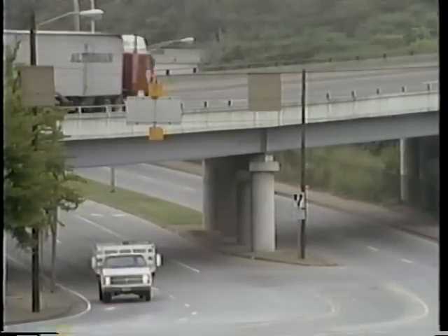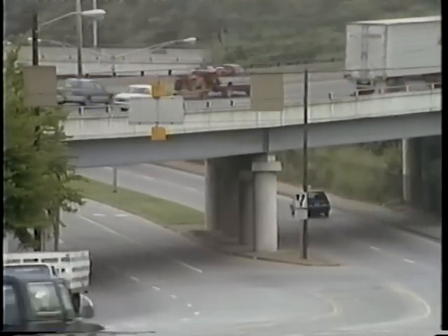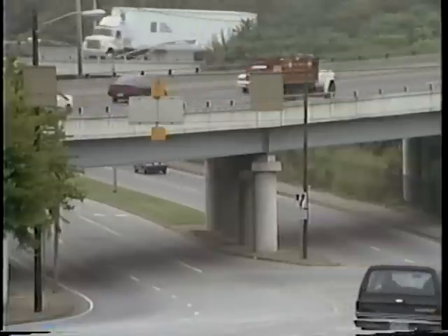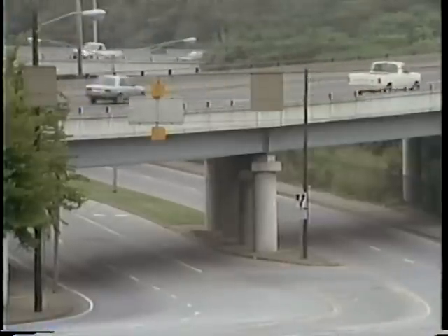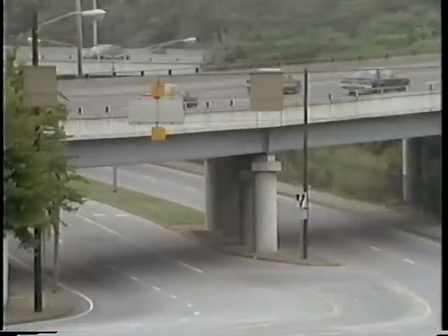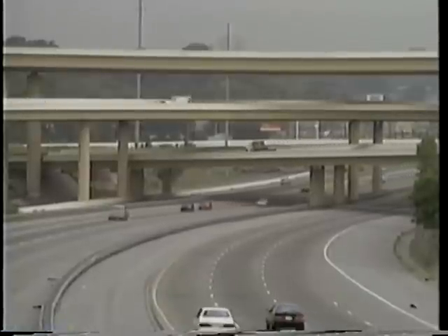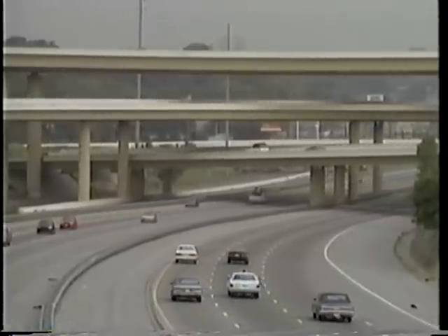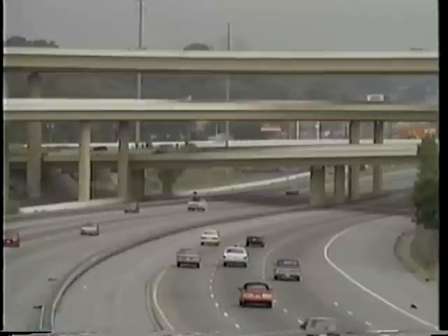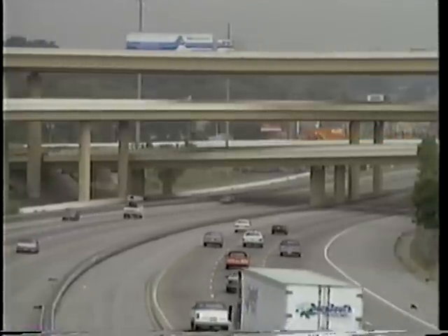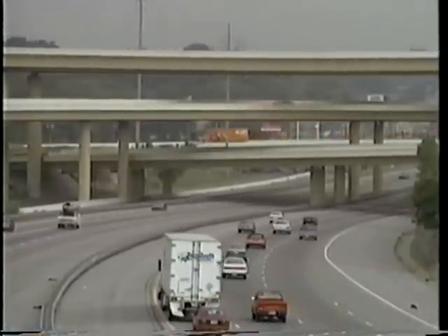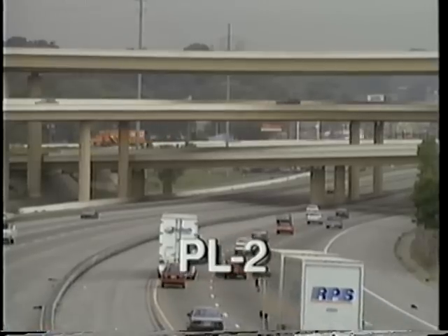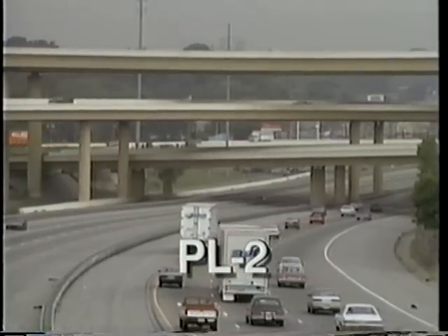A typical bridge in an urban area or on a highway carries larger volumes of traffic at higher speeds. Some of these bridges also experience more truck traffic. Because there is a greater probability of a collision and the collision is likely to be severe, these bridges require a more costly, higher performance railing. Most urban and highway bridges fall into this second performance level category, PL2.